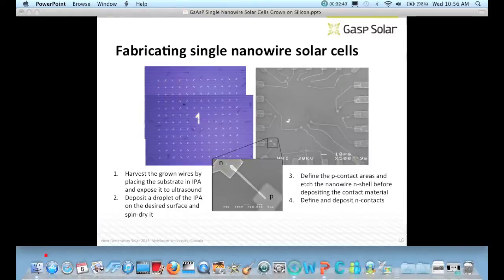And here I should say that the thickness of this nanowire at max up here is 400 nanometers. Now it's not standing perpendicular on the substrate anymore, so it's no longer absorbing a lot of the photons impinging on it. Because it's very thin, you can expect that half of the photons impinging on it will basically either be reflected or pass through. I don't know how much, but theoretical modeling says that up to 50% of the photon flux coming in will either pass through or get reflected.